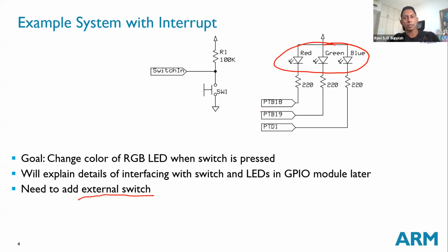As I mentioned, soldering is very important. If you don't do it properly and the solder spills over, it might cause a short circuit within the pins, or you can even damage the board. For the soldering part alone, you can always approach someone else in the lab who is more proficient and can help you.